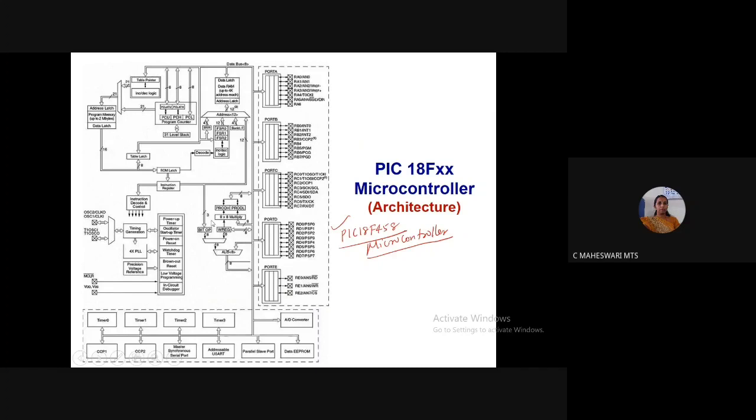To fetch the instruction, the instruction register is used, and instruction decoding and control is used to decode the instruction. For the crystal oscillator, timing pulse is given. Then it has power-up timer, power-on reset, watchdog timer, everything is available. We will discuss each and everything later.